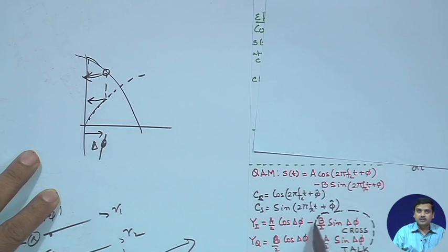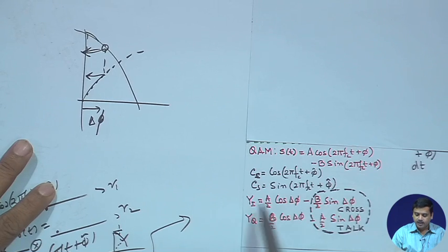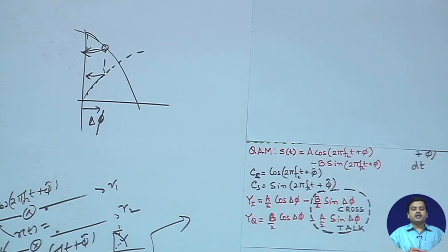So, what happens? There is a huge amount of interference, and what we have is a crosstalk appearing in the I channel and the Q channel. The in phase produces a component on the quadrature phase and the quadrature phase produces a component on the in phase. So, as there is relative phase offset between these two, this is also sometimes known as, no, this is not the IQ imbalance. Because of the phase offset between the transmitter and the receiver, some components of the I channel get projected onto the Q and some components of the Q channel get projected onto the I. So, there is crosstalk, and this not only causes interference, the desired signal power is reduced and interference power increases as there is a gap in phase.